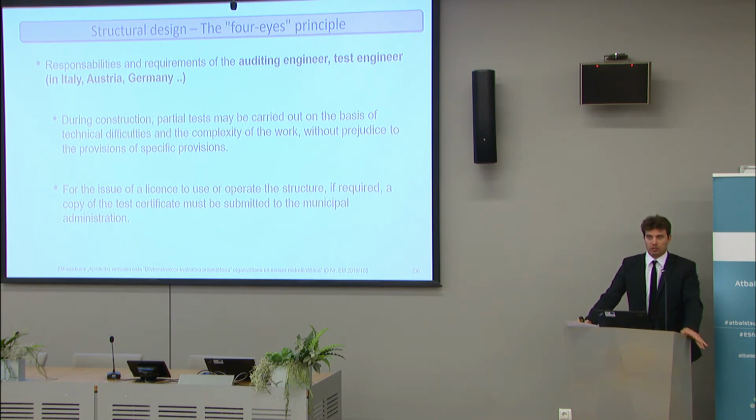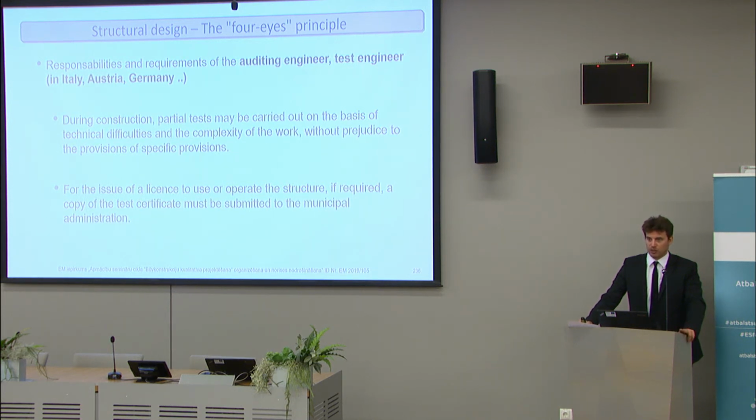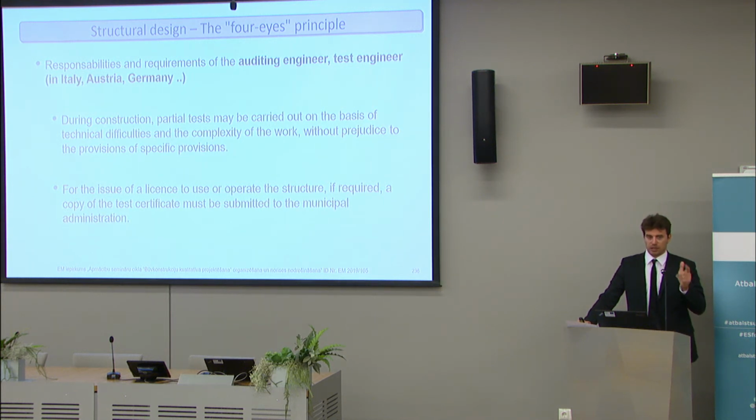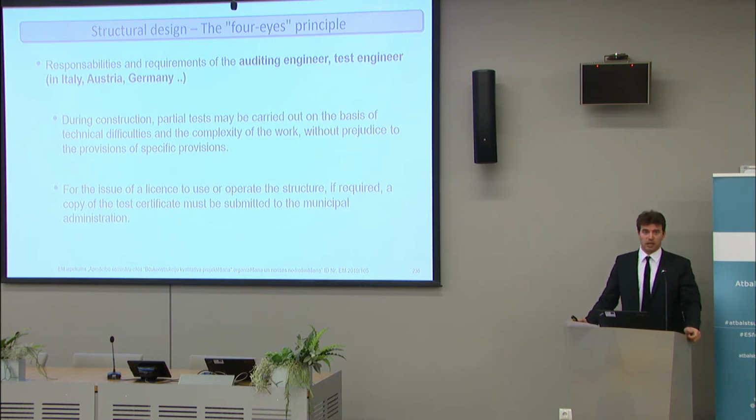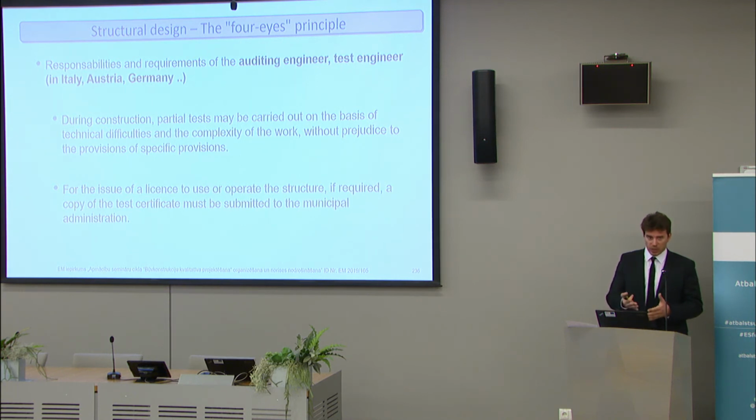So in our case, when at the beginning I was working in that company, I remember once, nothing is actually built before the approval of this external reviewer. I remember they were late, and they sent us late these reinforcement drawings. And in this reinforcement drawing, there was an error because the anchoring length was not long enough. They had a mistake, and so actually we called the construction company right away, where they were almost starting to build the